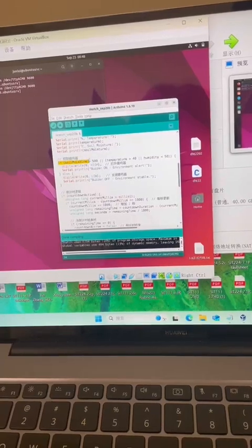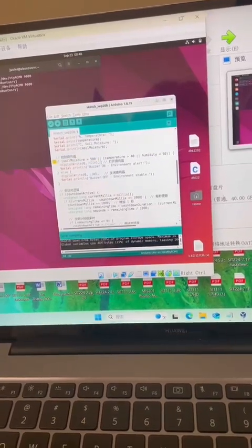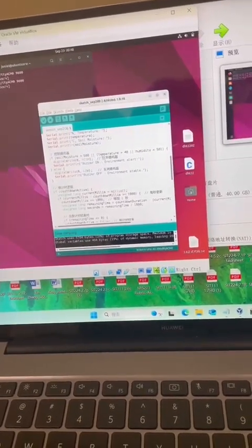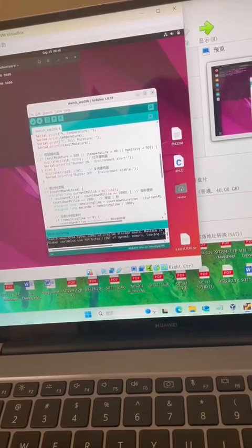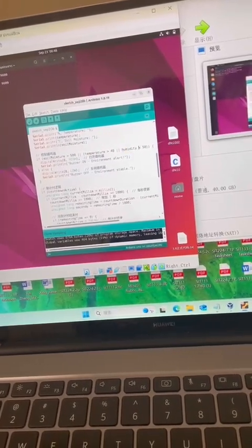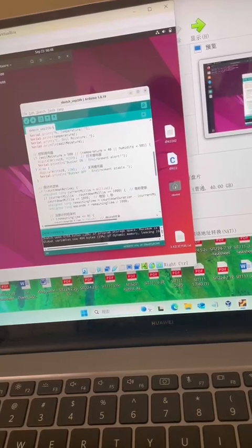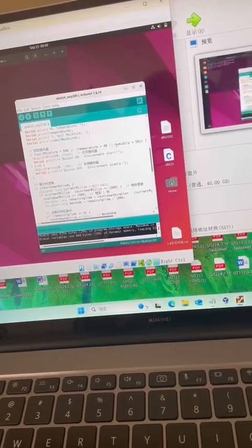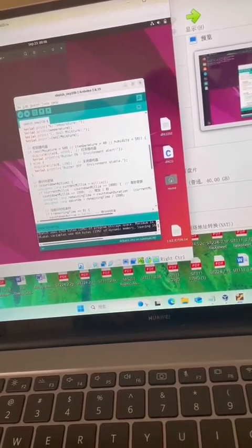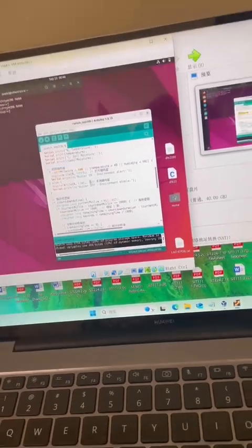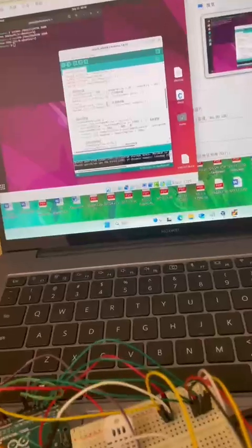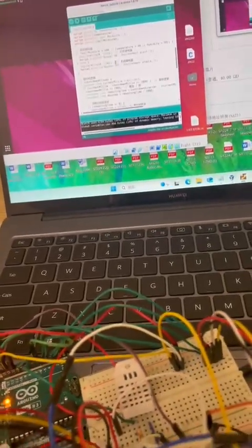If the soil moisture is bigger than 500, it will trigger the alert. The same goes for air temperature bigger than 40 and humidity less than 50, but those are conditions in the air that are very difficult for me to control, so I will control the soil moisture to show you how the buzzer responds.